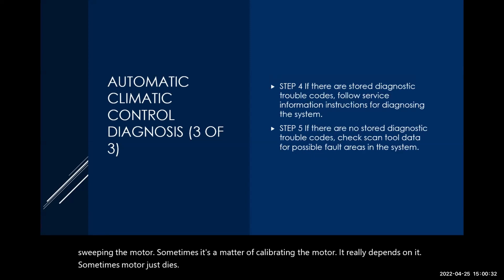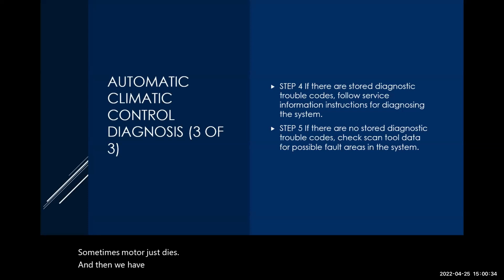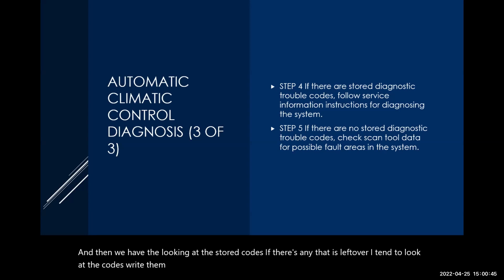And then we have looking at the stored codes, if there's any that is left over. I tend to look at the codes, write them down, and then clear them out, and then run it for a while to see if any codes come back.